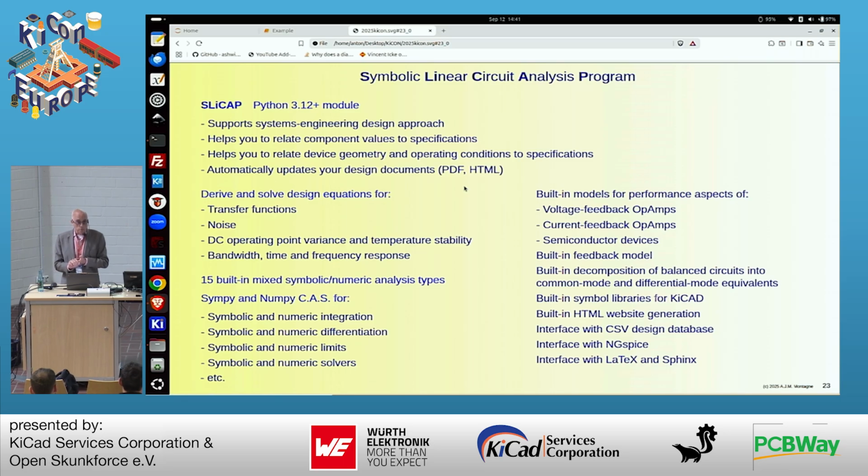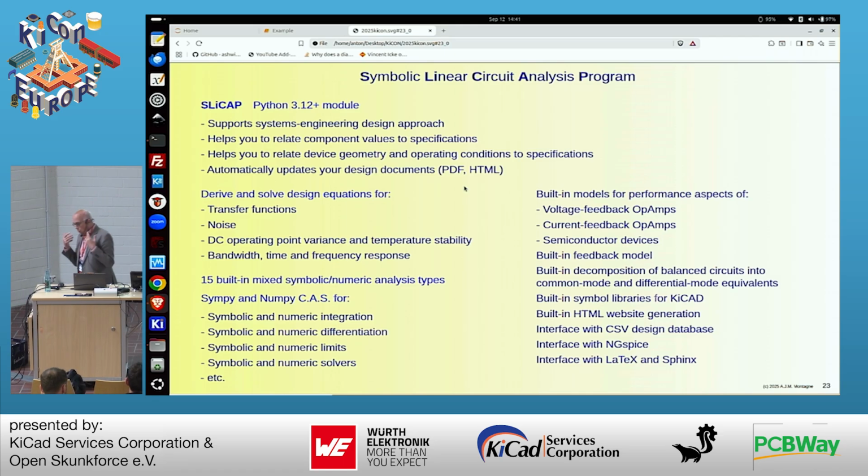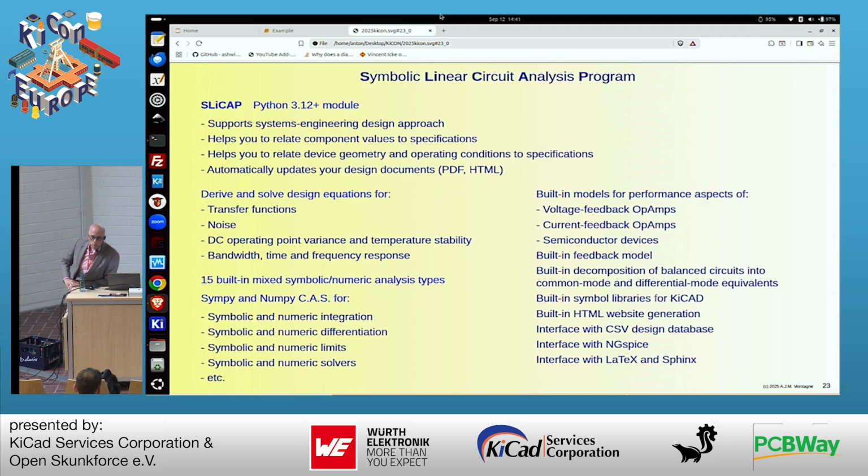Unfortunately, in SPICE, most macromodels of operational amplifiers have the offset of the op-amp as a fixed voltage source, which is useless, because the standard deviation is known, but the mean value is not. Yes, it can be 0, but it's all about standard deviation. So, for example, we need a design equation: what should be the standard deviation of the offset of my op-amp so that my voltage range at the output of the transimpedance amplifier is within spec? That's a design question. So we need to have that also.